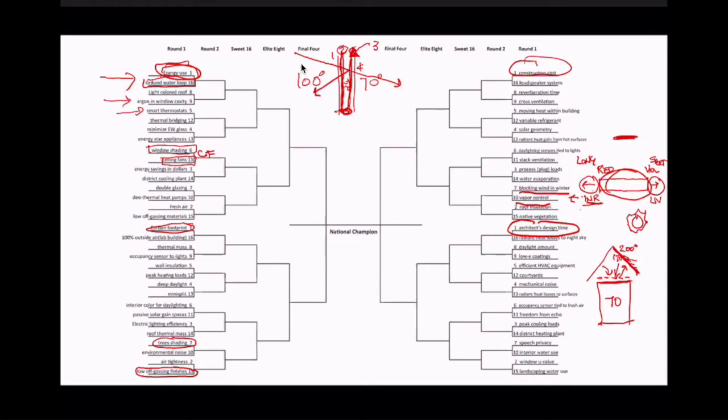But if you have ventilation at the eave of the attic and at the ridge of the attic, and there are code minimums for this, or if you have an attic fan, you can dry out that space. That space is made so that it can dry out if there becomes moisture. Typically, I think we're more concerned with moisture coming in from the rain than from condensation. Condensation would come on a cold day, I suppose.